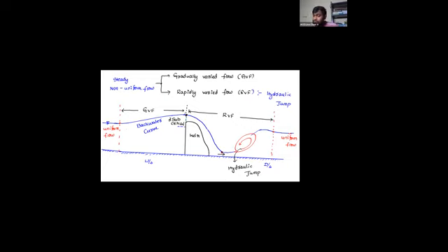Moreover, when the flow falls from this height, the potential energy is converted to kinetic energy. Energy is not dissipated here; it transfers from one state to another. So when the water falls from the top to the bottom, potential energy converts to kinetic energy, which means velocity is more and depth is less. Flow with smaller depth and larger velocity, here it is going to be supercritical.